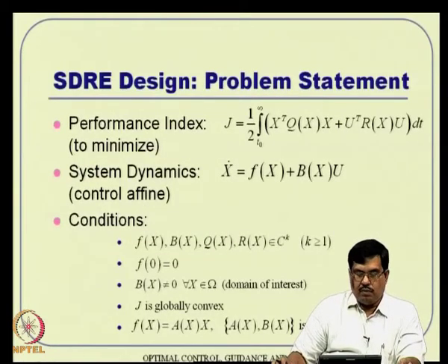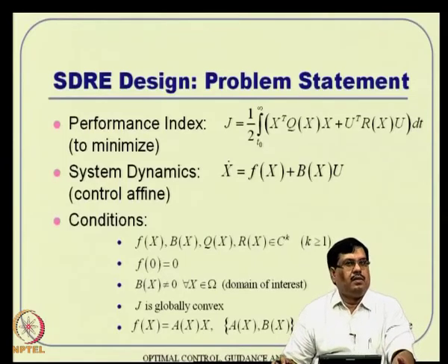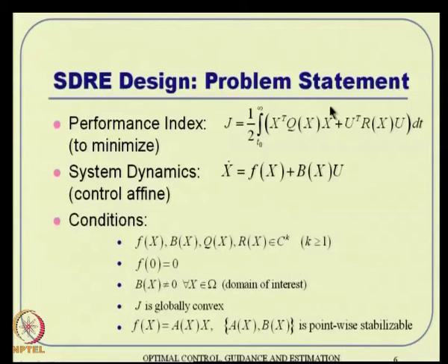Now, talking to this SDRE design problem statement, the first thing you are looking for is a performance index in quadratic form. Okay. So, very close to what we know in LQR design, especially infinite time LQR problems, where TF goes to infinity. But in addition we will also see that this Q and R can be functions of states also,